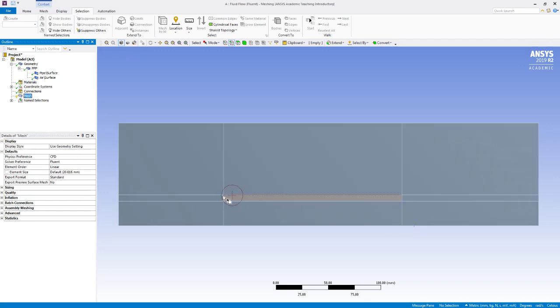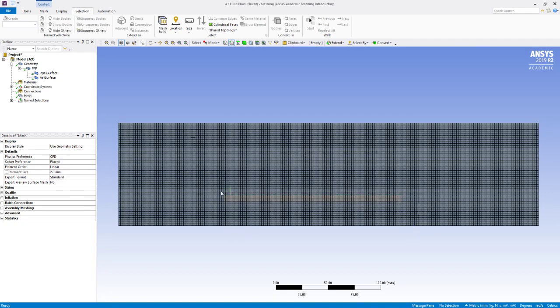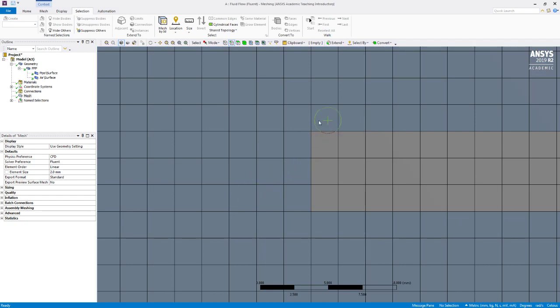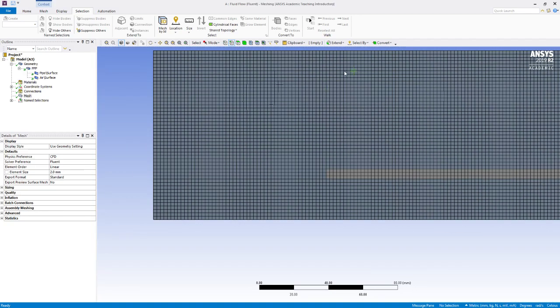And we know that this is 6 millimeters across here, so if we wanted 3 elements across, we'd have to go down to a 2 millimeter element size. And if we quickly did that mesh, we'd get a certain number of nodes and elements. But what we really want is to get nodes and elements closer. If we zoom in here, we want much smaller elements around here, and then out at this boundary we can have these large elements.